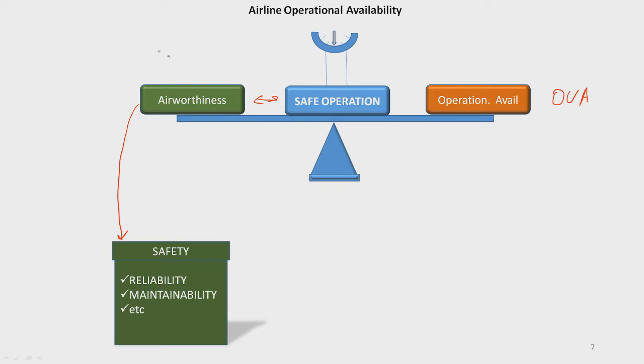Now, where does this assessment start from? The answer is very simple. From design. Next is testing. Next is manufacturing. Next are aviation authorities' regulations and requirements. When the product is certified, it goes to operation. You remember what we said in our definition? Maintain and support. So we have to maintain an appropriate level of airworthiness when we are in operation.